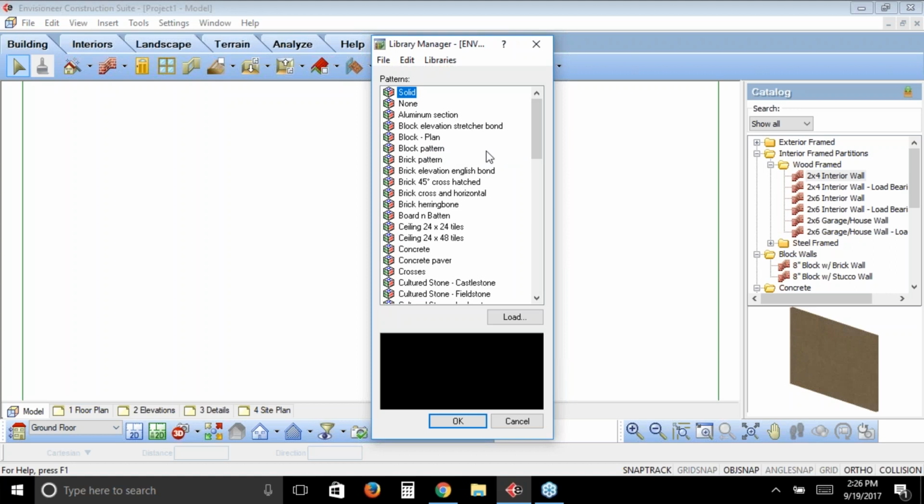So you could reorganize them again so that every time you apply a hatch pattern, if I'm always applying a horizontal siding hatch pattern, I have to scroll through to find it. I know it's only seconds, but it does take time. Maybe just grab it and move it to the top of the list. It's the exact same as working in the other one, so you can grab something and just move it along as you need to.